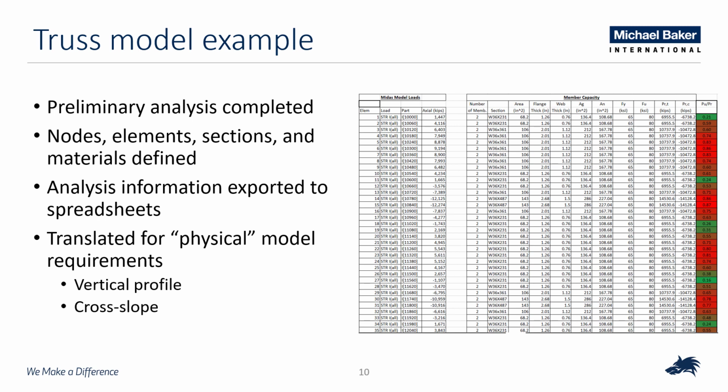So now that we have the information in our spreadsheets that is accurate and what we need for our physical model, we want to look at how we can efficiently create our model, right? Our nodes, some of those repeatable tasks, right? You saw how large that truss was. Do we want to make sure we're connecting every single node, every single beam, truss element to every gusset plate, right? And also, not only is that a repeatable task, it's also very time consuming and tedious, right? So we want to take this information and generate it now to a physical model that we can use for additional benefits, additional tasks afterward.